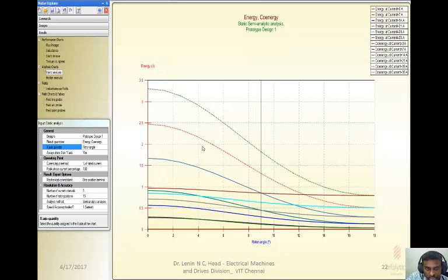So far, what we did is finish the static analysis. In the performance chart we see flux linkage, inductance, static torque, and in static analysis we have energy and co-energy. Based on that, it is possible to find the operating point of the switched reluctance machine. And in fields we have different instantaneous fields: flux density, permeability, current density, winding losses, everything. Up to this stage, whatever changes or optimization you want to do, you can carry out here itself. No need to go for transient analysis.